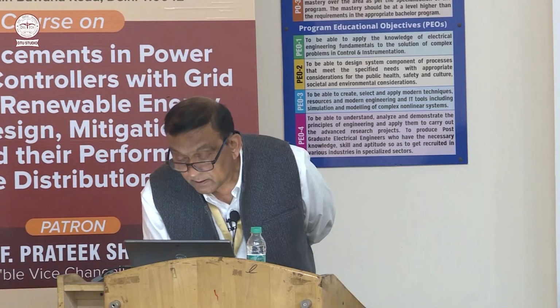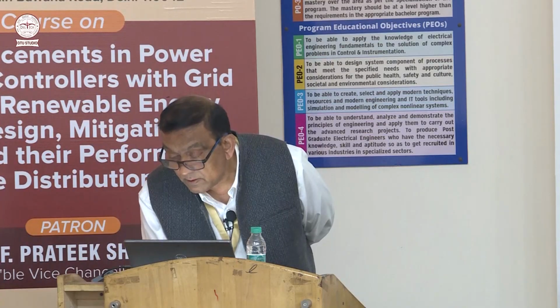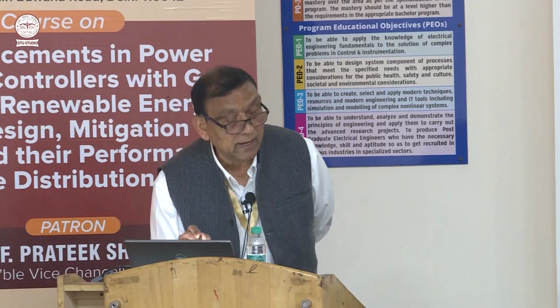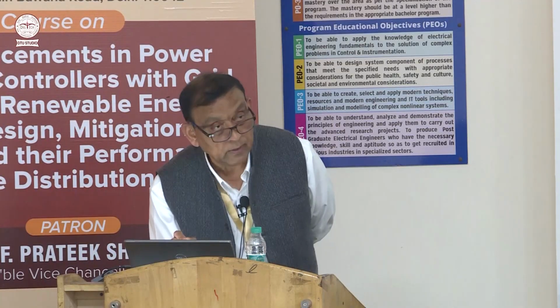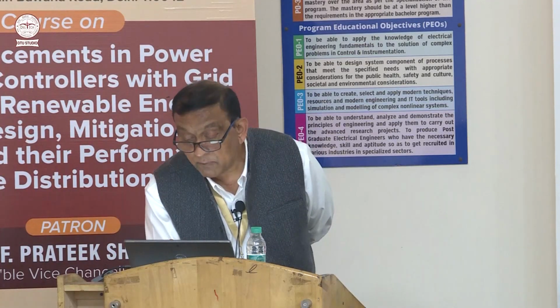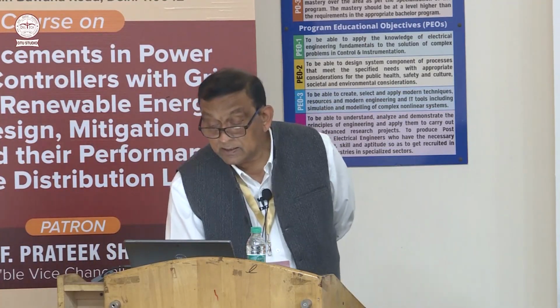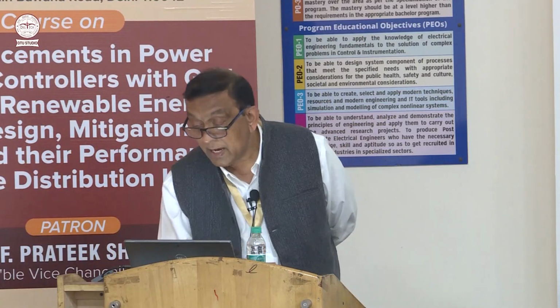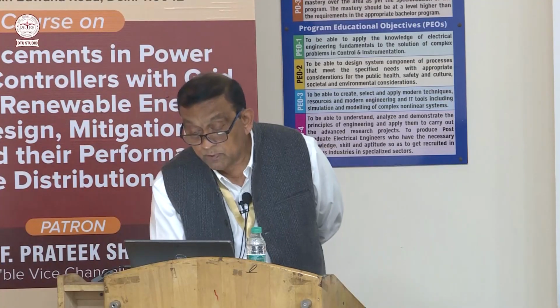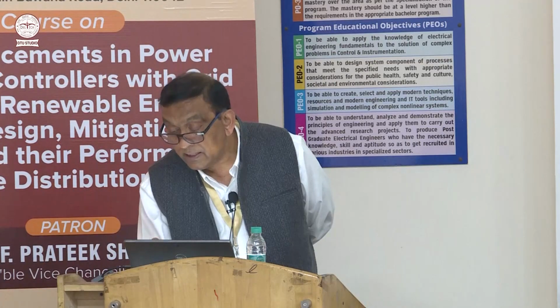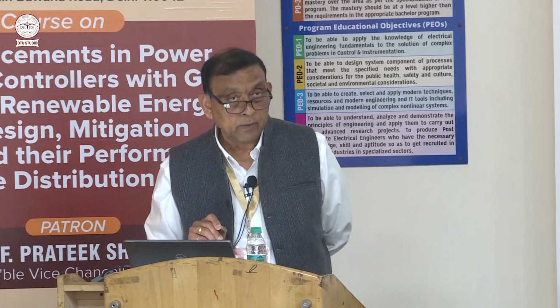NL multiplied by IM, and then here you have I3M current in this winding. And this you can say number of turn NS, because it is small winding, or this is large winding, and this is on primary side. So all these three are on the same leg. So sum of all this MMF should be 0.